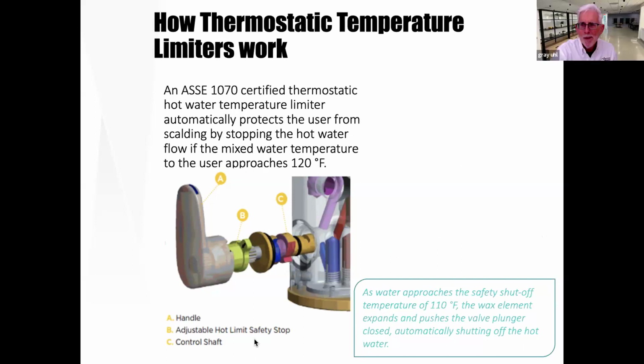One other thing I'd highlight here, just as we're talking about thermostatic elements in general, we mentioned the wax element. That's one of the newer technologies over the last couple of decades. Previously, there was a lot of bimetallic on the market, and then of course there are mechanical mixing valves for point of use as well that don't have that thermostatic adjustment. So just something to keep in mind as we're talking about the generalities of it. There is wax and bimetallic and these other methods, but most of the point of use ones, and I think this is true across manufacturers, are going to be a wax element.